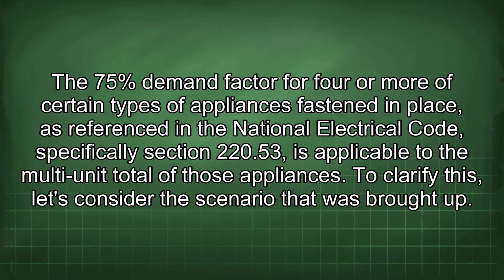The 75% demand factor for 4 or more of certain types of appliances fastened in place, as referenced in the National Electrical Code, specifically Section 220.53, is applicable to the multi-unit total of those appliances. To clarify this, let's consider the scenario that was brought up.